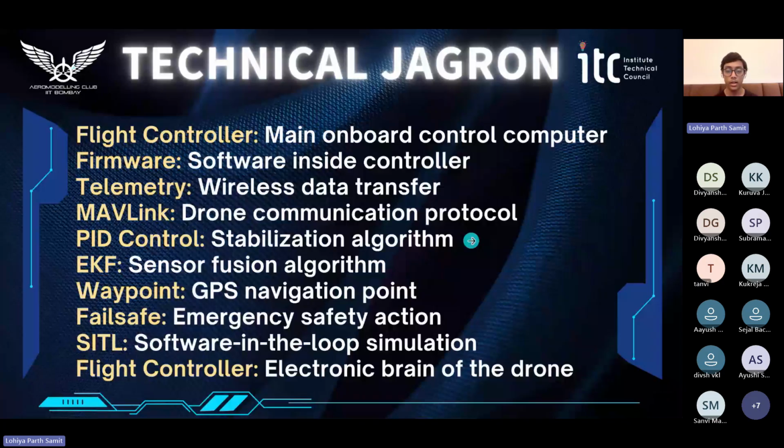EKF, that stands for extended Kalman filter, is a sensor fusion algorithm that fuses readings from multiple sensors and gives an accurate output. A waypoint is just a GPS navigation point. A failsafe is an emergency safety action that must be implemented in your drone systems.